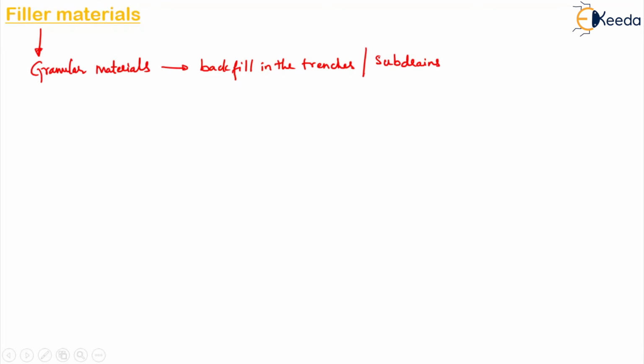If the free water has to reach the drainage quickly, the filler material must be many times more pervious than the protected soil. However, if the filler material is too pervious, the particles of the soil to be drained are likely to move into the filler material and it will get clogged. The top of the drainage trench in which the filler material is placed must be properly sealed, because the surface runoff generally will contain some silty material, and if it runs into the filler it might clog the pores and reduce the efficiency of the filler.